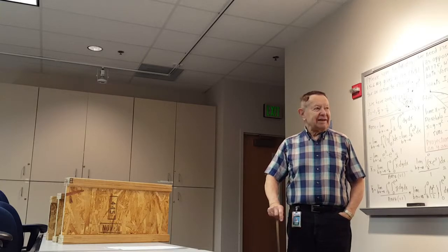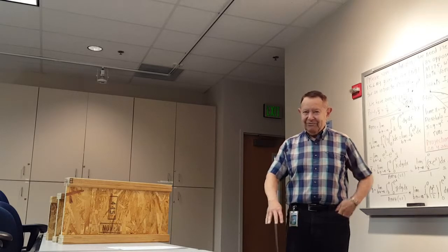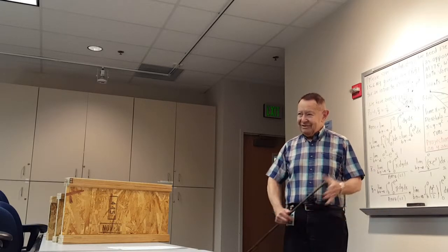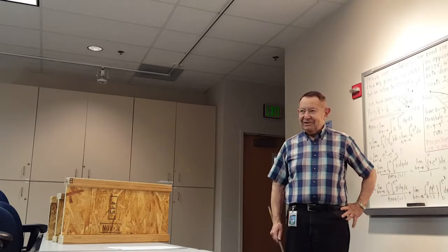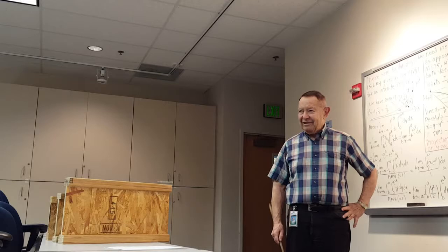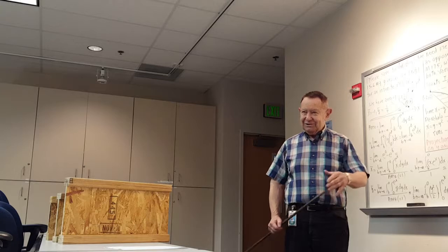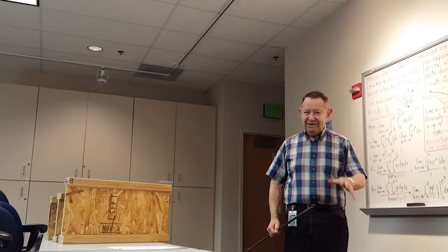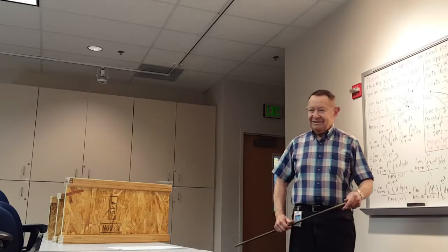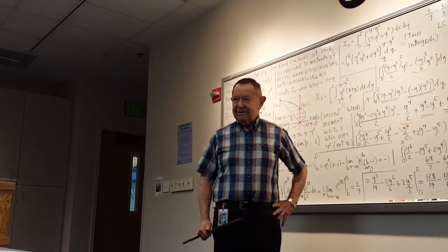In times past anyway, when people were taking stock things, say like Ford's, the old flathead Ford V8 of the 30s and 40s and early 50s, if you wanted to make the thing accelerate faster, you'd machine the flywheel down, among other things, because it'll wind faster the less inertia you have to overcome. On the other hand, it becomes harder to drive because it makes it easier to kill, because you don't then have that flywheel to keep you going.